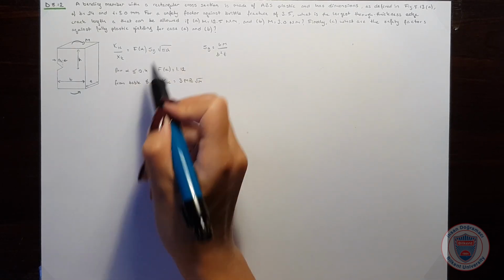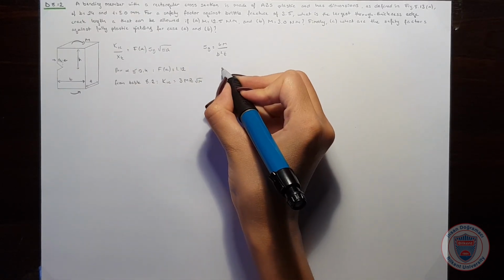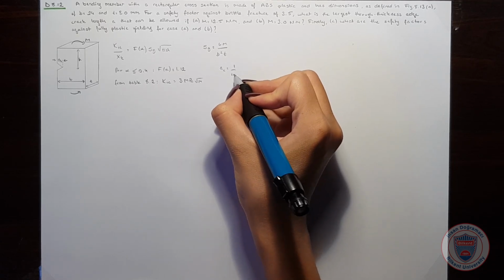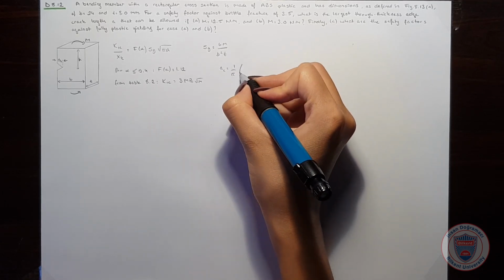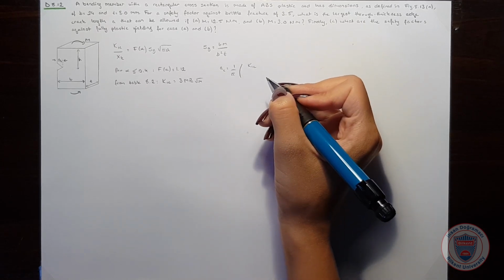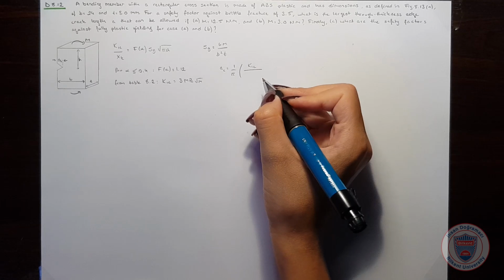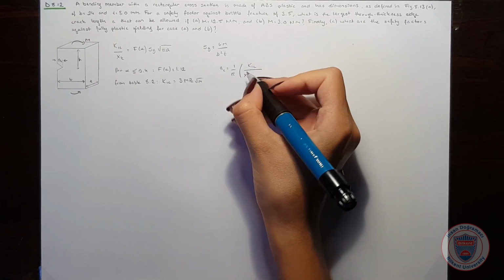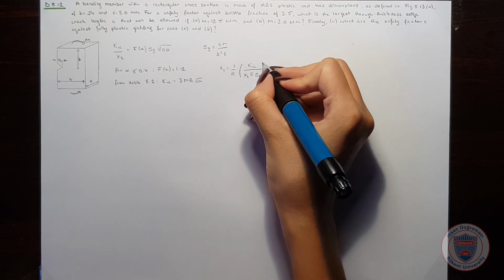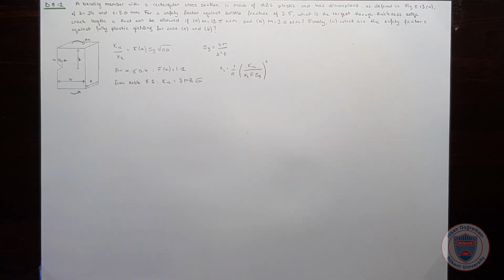And considering this equation, we also know that the critical crack size will be 1 over pi times the critical stress intensity factor over safety factor times the form factor times S gross, squared. Now let's start with part A.